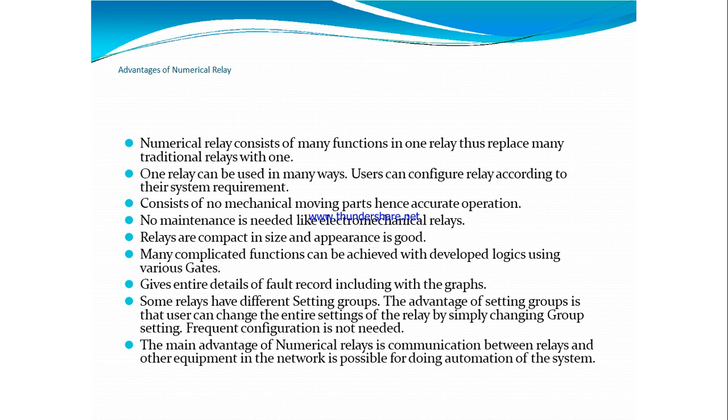There are no mechanical moving parts, and hence wear and tear problems do not occur, and it is compact in size, so the aesthetic look is also better. Many complicated functions that arise while using gate circuits can be handled in such cases, as a numerical relay may provide a solution. It gives the entire detail of the fault record including graph details, so we can easily observe and infer what type of fault has occurred, when it has occurred, to what level it has occurred, etc.